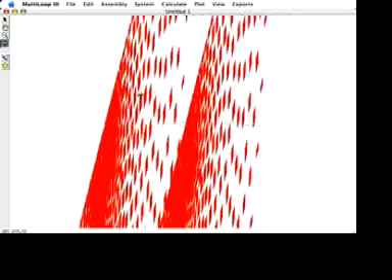Let's take a look at our work. The dark line indicates the location of the traverse line, and we can use the manipulators on the left-hand side to move ourselves about in the 3D space. The traverse line looks a bit short, so let's go back and change it. So we're going to change the start point. Again, let's change the number of stations so we can keep our station interval nice. And then we hit OK. And here's our new traverse line.